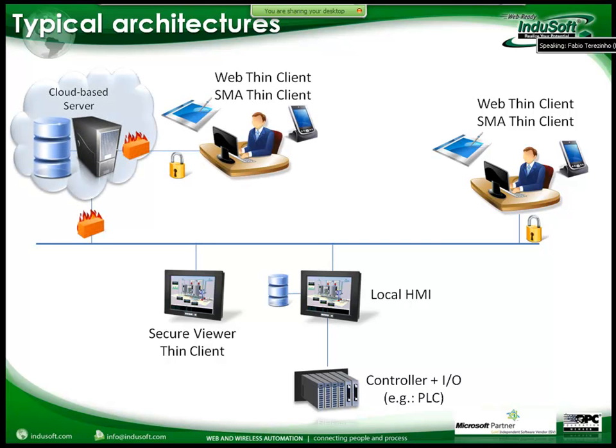We are seeing more and more customers requiring this kind of architecture, and we have deployed many successful systems like this, where you have different RTUs, different buildings, different stations, but we consolidate information from all those sites to a central server, which typically is running on the cloud. So the local InduSoft Web Studio is collecting data from the sensors, saving data locally, and if the link with the cloud is good, forwarding the data to the central server on the cloud.